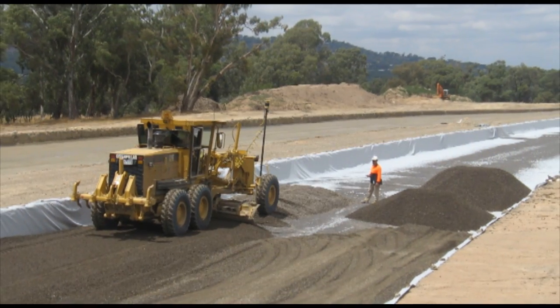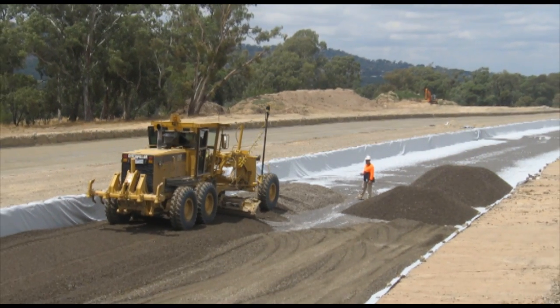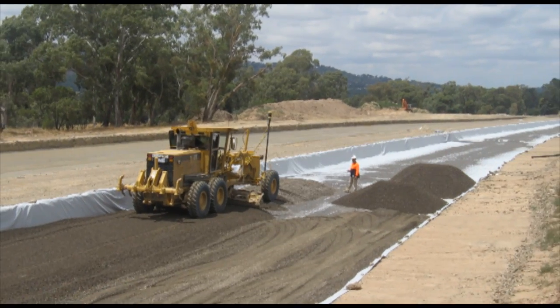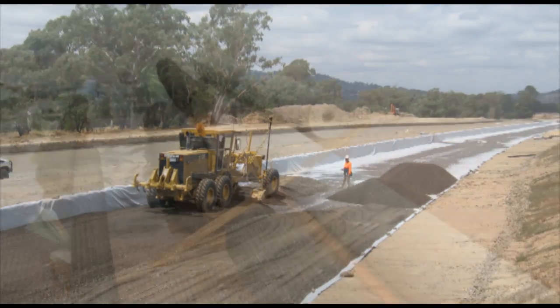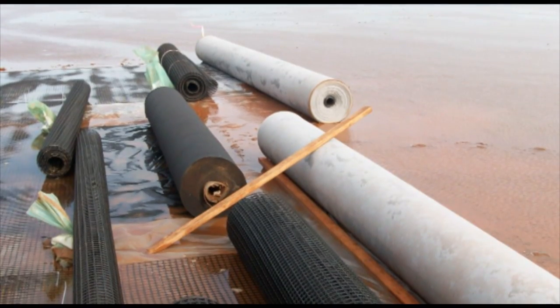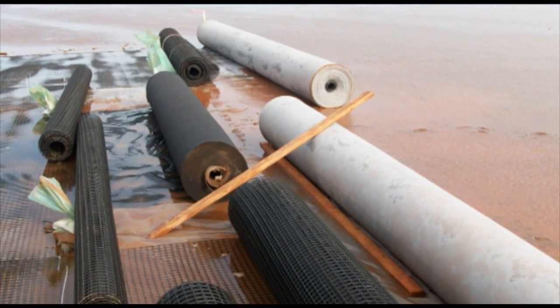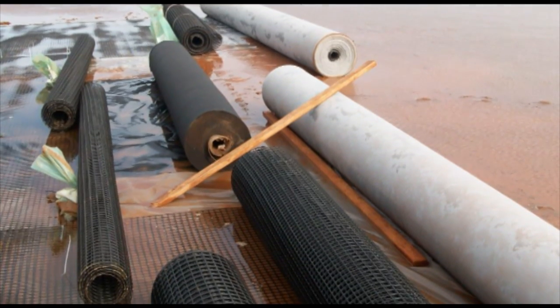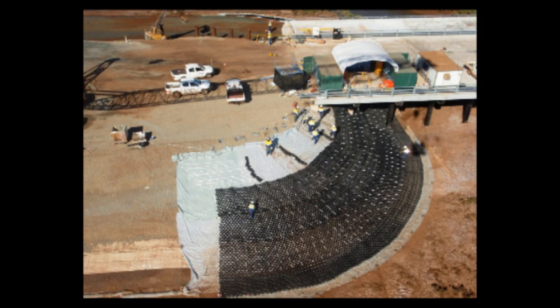As well as separating the weak soil from the introduced road aggregate, the geotextile allows water to drain from the road formation. Geotextiles can be found in combination with geogrids or other geosynthetics on extremely weak or waterlogged soils. They are also used in other civil infrastructure, in this case a bridge abutment. The geotextile is placed underneath a geocell to protect the abutment during flood conditions.